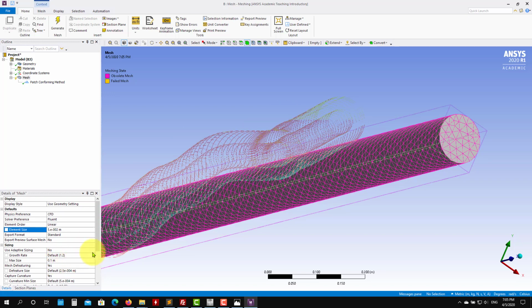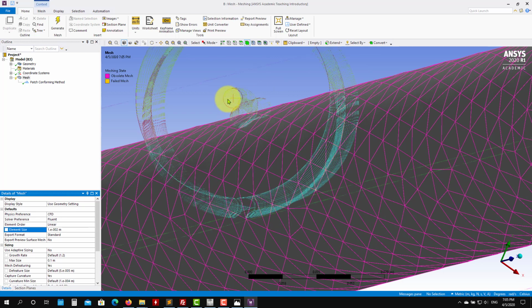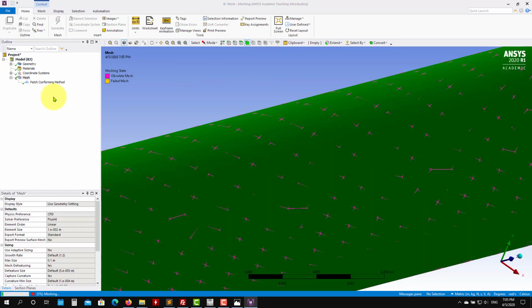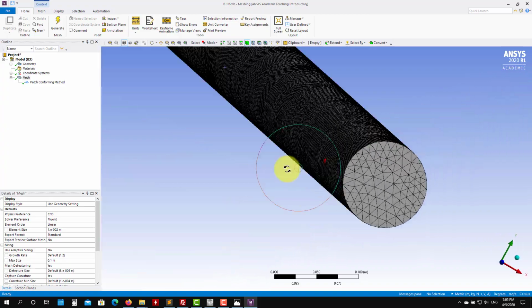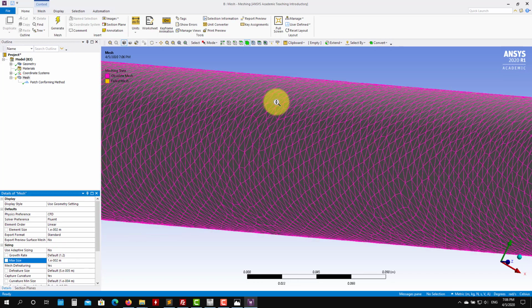Okay, here are some other functions that we're not using, okay? So let me put 0.01 and see that the inner one represents your tetra dimension. But that is global, okay? Global parameter. Let's do the mesh. So probably this one will take longer because it's smaller cells. So let's see. Okay, so see that a nicer mesh, okay? So remember here, control these parameters. Let me put this one 0.1, probably see that you have.